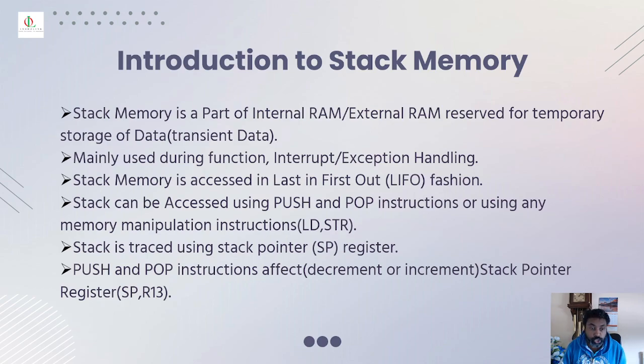With the help of push and pop instructions, when you store and retrieve data, it affects the increment or decrement of the stack pointer. You will learn that in the coming slides, and you will understand more about push and pop. The stack pointer will show you the current stack location, and that will be the R13 register, which you will learn about in the next one.